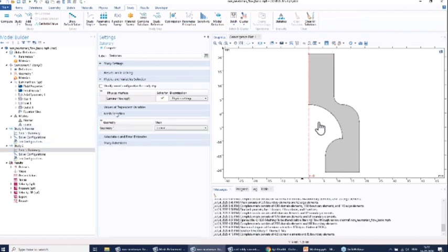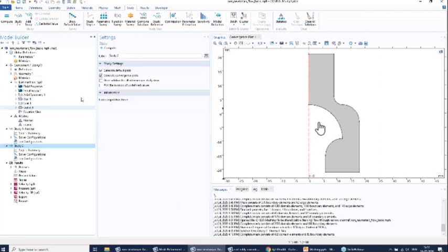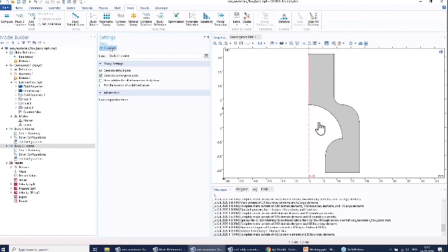In the stationary study, you will get this mesh selection. Make sure that the coarse mesh is selected. So you have an option where you can run your model with different meshes. In the label also write coarse, like last time we wrote normal. And compute it.